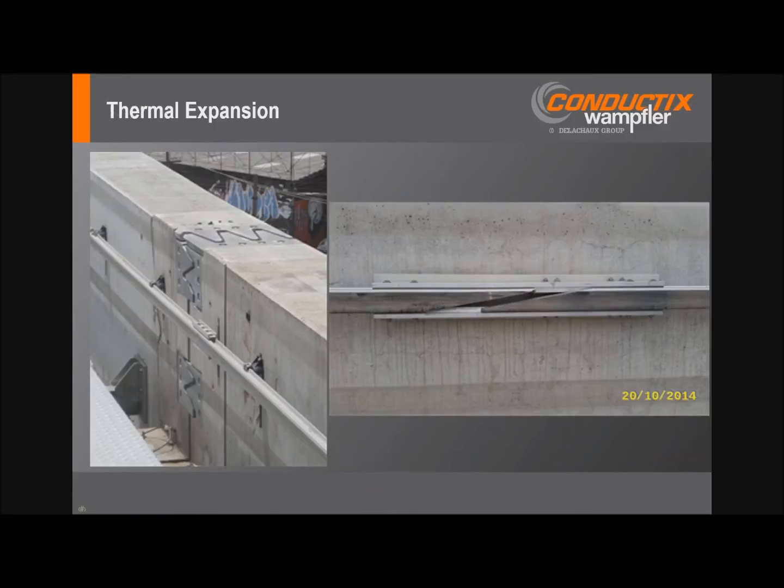Thermal expansion is a big consideration here, both in terms of the absolute ambient temperatures and current heating of the conductors, as well as the relative movement of the conductors to the guideway. Poor expansion management can lead to all kinds of problems: conductor snaking, breaking hangers, and it can sometimes be so severe that the collectors are unable to maintain contact with the power rail. So it's really important that the guideway expansion joint movement is considered along with the conductor thermal movement when designing this.